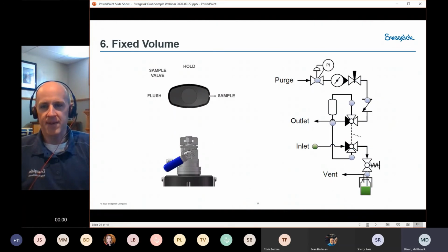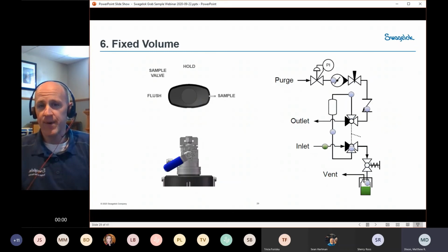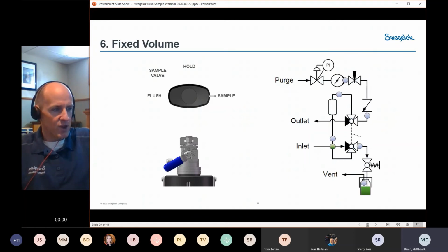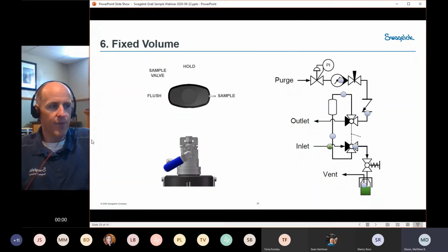Is it 1000 psi? Now, for some people that threshold is a bit less, maybe a few hundred psi. But in general, I think we're pretty comfortable with up to 1000 psi, because this valve actually does have an orifice in it. So we're able to knock the pressure and flow rate down using that orifice rather than having to rely on throttling the valve.